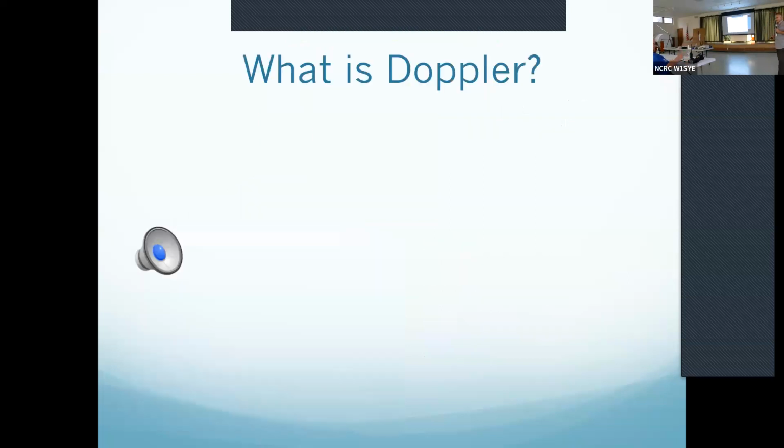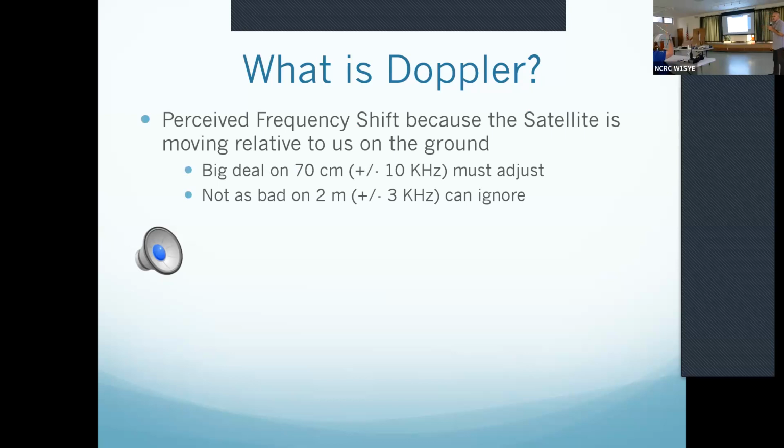I've actually done satellites with just doing horizontal. If you don't have circular, you can switch back and forth. I got a 2 meter beam that's vertical, horizontal, and I've worked satellites doing that. Before, I had a 441, a short little 9 element, and it worked. You can do it with flat ones. It just works a lot better with circular polarized. If you have horizontally or vertically polarized, it'll still work, but you might get some cutting in and out, or the voice will go lower or something like that.